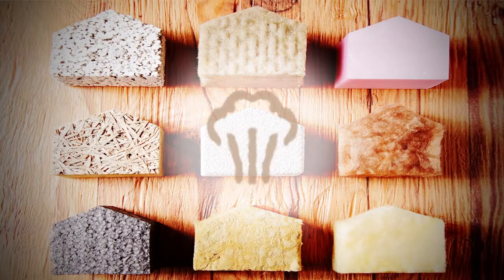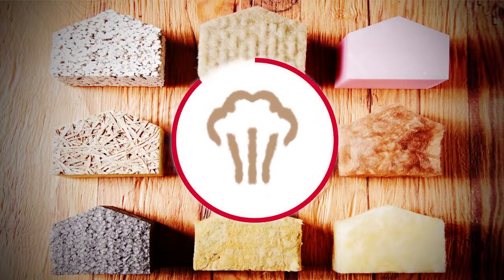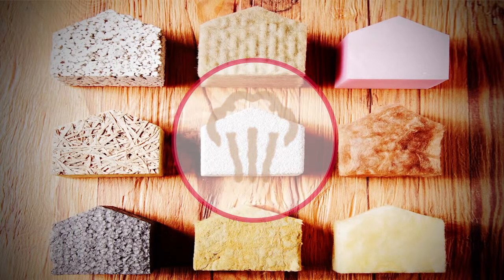The first of these challenges is that older buildings typically benefit from highly vapour-permeable insulation. This is because traditional building materials such as lime-based mortar and plaster have very different hygrothermal properties from their modern equivalents. Adding insulation of low permeability, such as rigid foam, on top of such materials can lead to damaging moisture problems for two primary reasons.